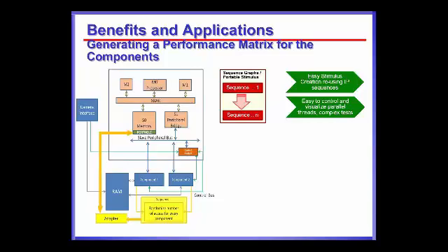But first of all, the benefit that we get out of this kind of approach is that we could reuse our IP level sequences and put them together to make an interdependent data path, where multiple IPs are involved, and create a sort of sequence graph, by combining all these sequences for independent IPs, right?